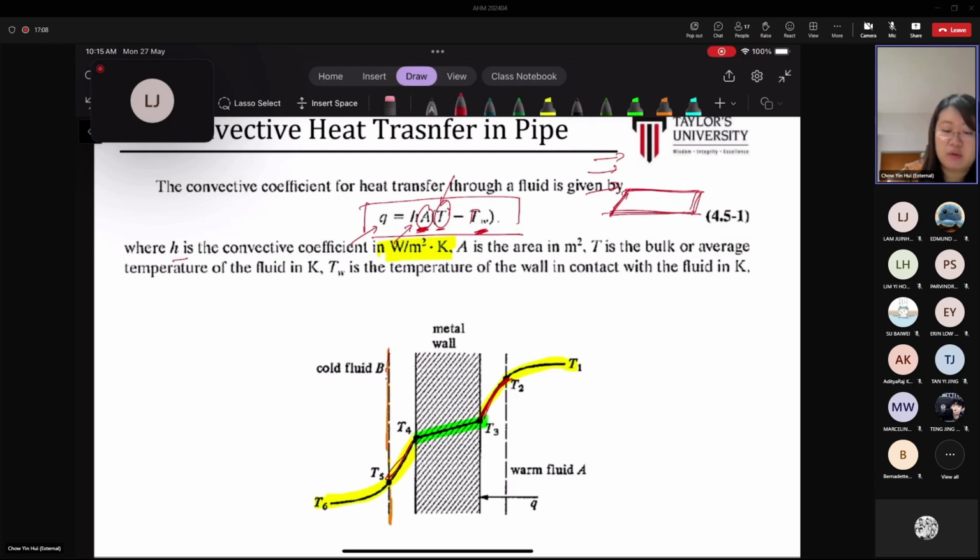That's where, if you compare to the velocity profile, usually there would be friction to fluid flow. So at a region which is very close to the surface, most of the heat will be transferred by conduction, because the fluid flows at a very slow rate. The same goes here.